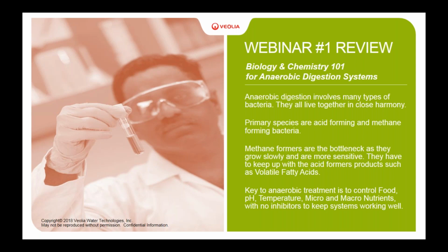In our first webinar, we went over the basics of the biology and chemistry of an anaerobic digestion system. Anaerobic digestion involves many different types of bacteria all working in harmony together, the primary species being the acid-forming and methane-forming bacteria. The methane formers, or methanogens, are the slow-growing, more sensitive bacteria. Those are the ones that we like to keep happy in the system in order for the anaerobic reactors to work well. The acid formers are the ones that produce the VFA for the VFA testing that you do.